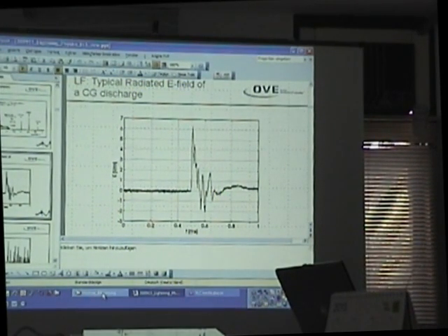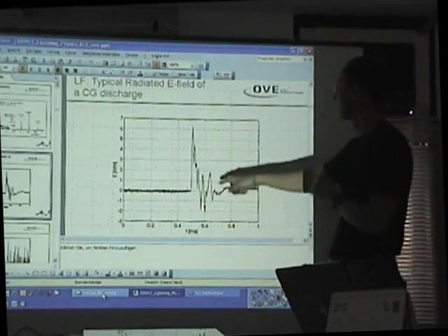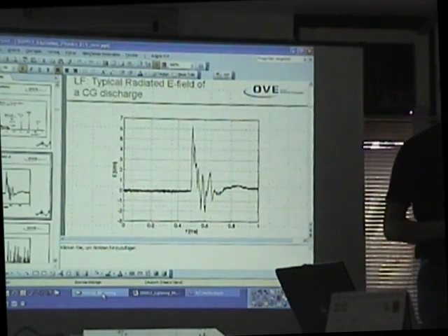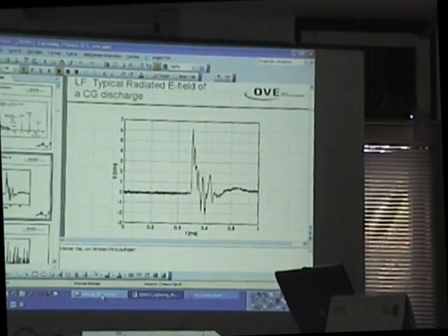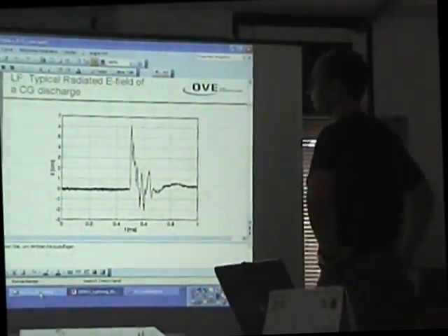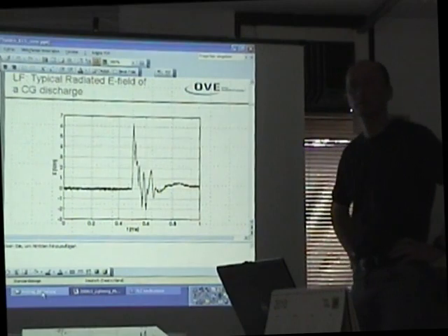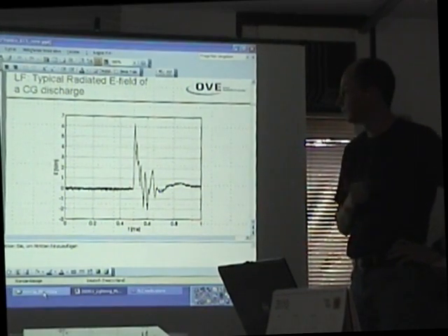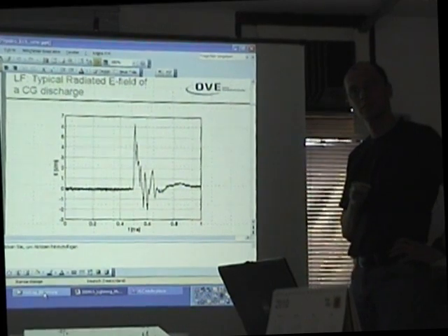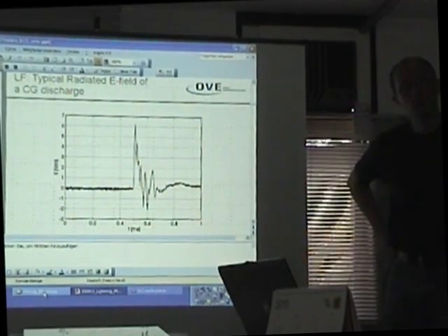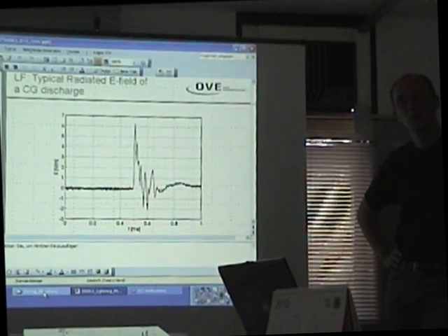Considering all this complex signature of the return stroke, the models, all the engineering world, just consider the first fast rising front for the peak current. Yes. But sometimes when you zoom on the structure, you also see some fast rising as sharp as the first one, just 20 microseconds after the beginning.